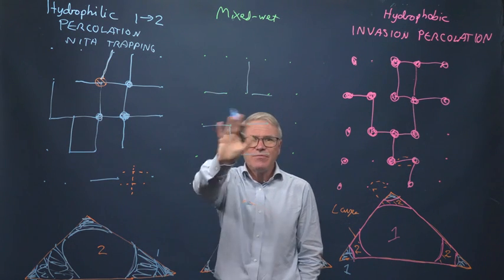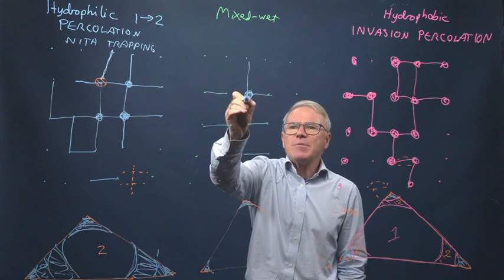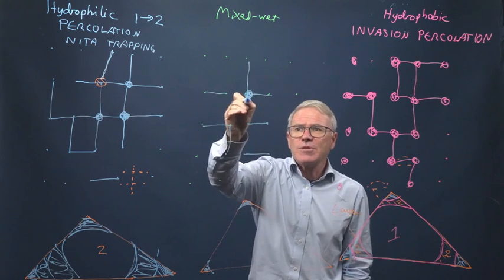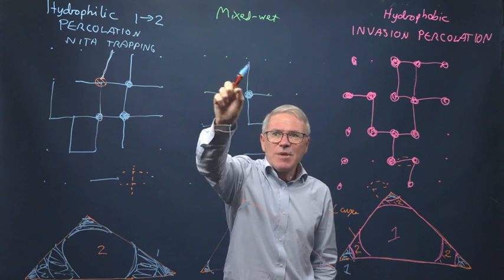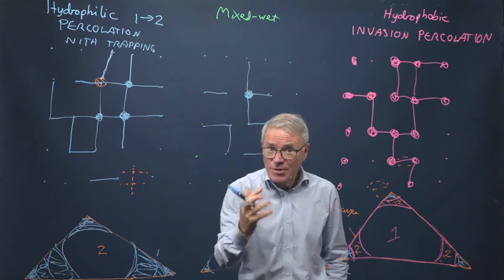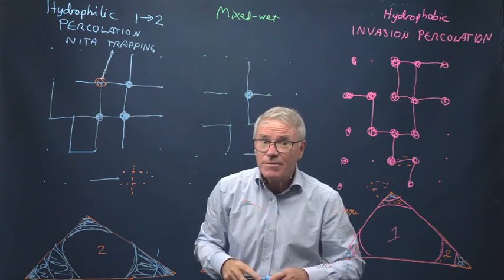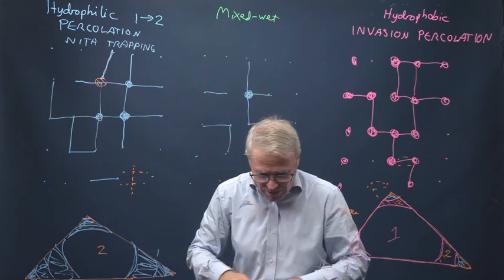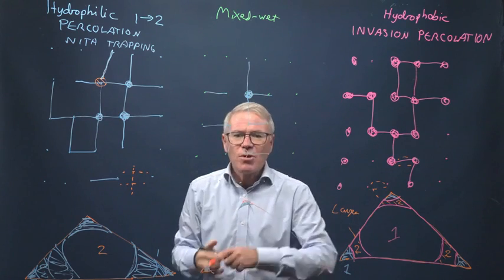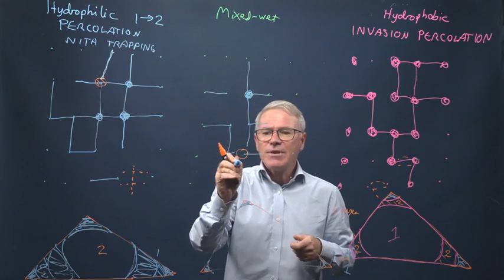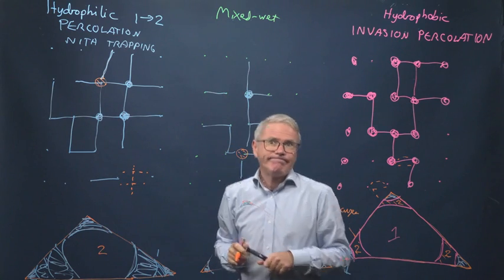Now imagine this is most of the water wet region of the pore space. Maybe you fill a pore, but not necessarily all the throats, because this throat may be a hydrophobic throat, so it's not favourable to fill straight away. So those are the water wet regions of the pore space that you filled. You might also get some trapping. You can imagine a case where this is a pore here, and just by snap off I fill these. But this is trapping, so you can get something that's trapped.